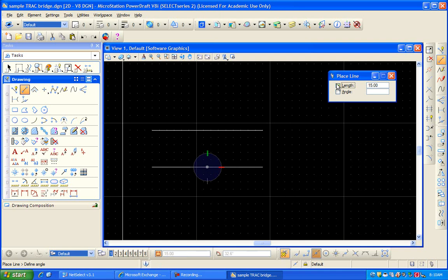And really, to be honest with you, the length of this line isn't critical because this is only kind of a temporary line. But I do want it to be straight up and down, but it's not allowing me. It's allowing me to pick the midpoint there, but up here it's not, and that's because I left the grid lock settings on, which forced all the elements to want to be drawn to these points.